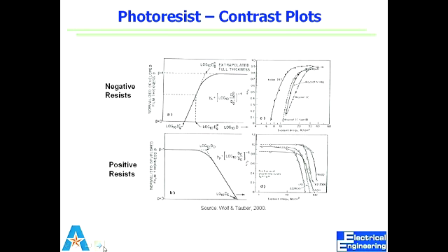Is it the border of the soluble and insoluble regions? It's not the border, it's during that whole conversion, what happens to the sidewall? How do the sides of that exposed area change? In the case of negative resist, the change is much more pronounced on the sides. So you get a much wider sidewall which has a much smaller angle. So you get a sidewall like this. In the case of positive resist, you would get a sidewall which would be much more at a right angle from the surface.